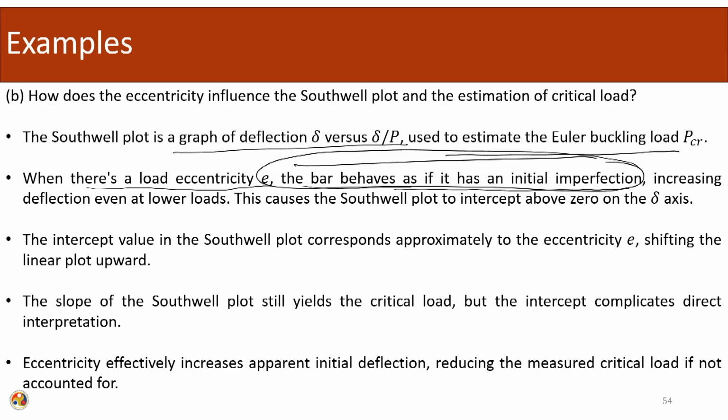What it will do is increase the deflection even at lower loads. Since there is an initial deflection already present due to the eccentricity, the deflection even at lower loads is more. So, it will cause the Southwell plot to intercept above 0 on the delta axis.